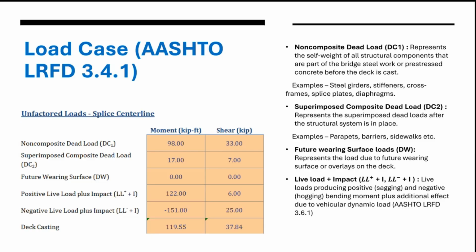You are saying not for the capacity? The moment and the shear depend upon the capacity of the section, what moment and shear we can get at that particular location. Somebody can look in the design manual. I think splices should be designed for the capacity of the members, since they are transferring that moment, right? There are some manuals which do require that.